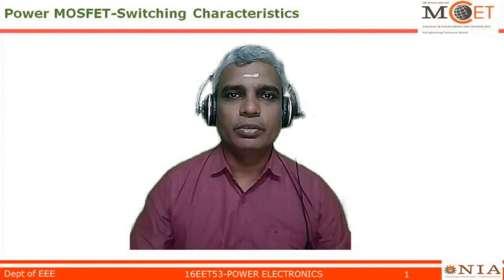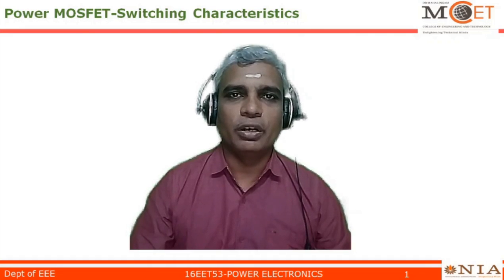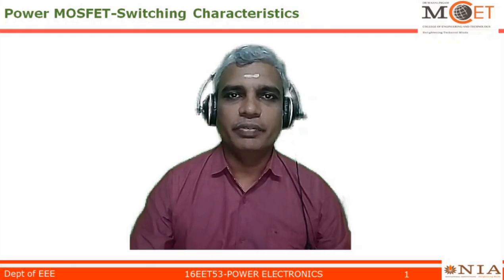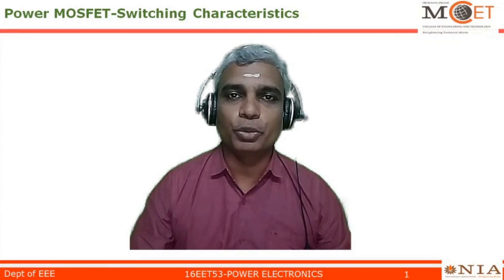In the previous video, we discussed the symbol, construction and principle of operation of the power MOSFET. Also, we have seen the transfer and output characteristics. In transfer characteristics, we fixed the value of VDS and varied VGS, and we plotted VGS against ID, that is the drain current. And in that, we understood that there is a voltage called VGST, that is the gate to source threshold voltage, above which the device turns on, which means that the drain current increases very rapidly above VGST.